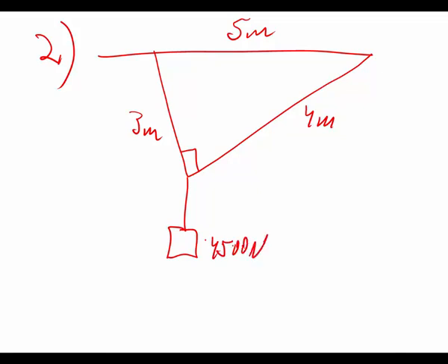Are you watching? Now, it says we got a cable system hanging from a beam configured as shown in the diagram below. A 4,500 newton weight hangs from the cables. What is the tension in cable 3? I'm going to label this T1, this T2, and that right there T3. Is that okay? That's really how you need to label them too. So we've drawn it, we've labeled it, free-bodied it.